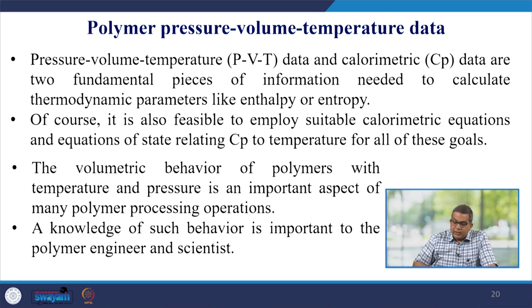Now, the calorimetric data, the Cp data or Cv data, are again very important. And these two, the PVT data and the calorimetric data, are the two fundamental pieces of information needed to calculate the thermodynamic parameters like enthalpy, entropy, all those things. Now, it is also feasible to employ suitable calorimetric equations and equations of state relating Cp to temperature for all these goals. Now, the volumetric behavior of polymers, with respect to temperature and pressure, is an important aspect of many polymer processing equations. So, such behavior is important for any polymer engineer or scientist.